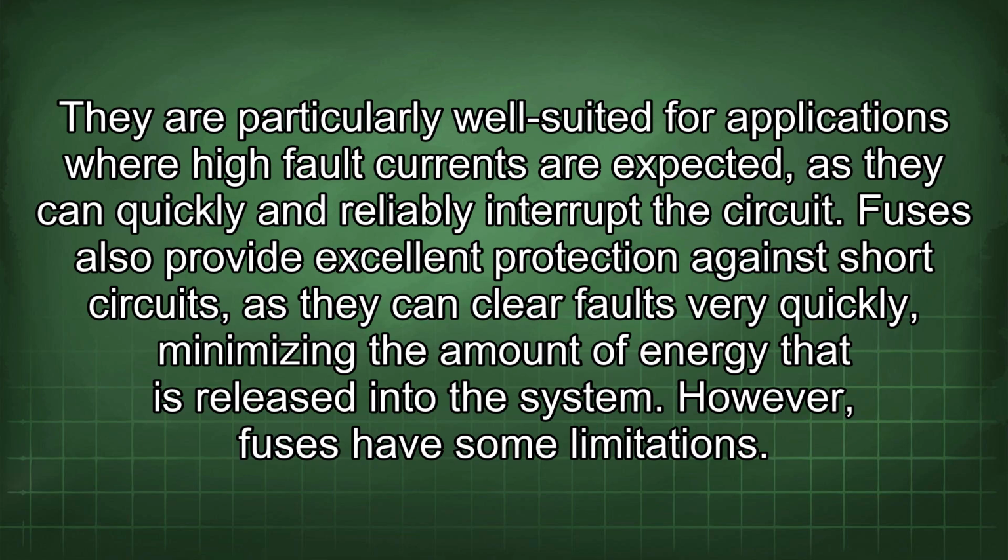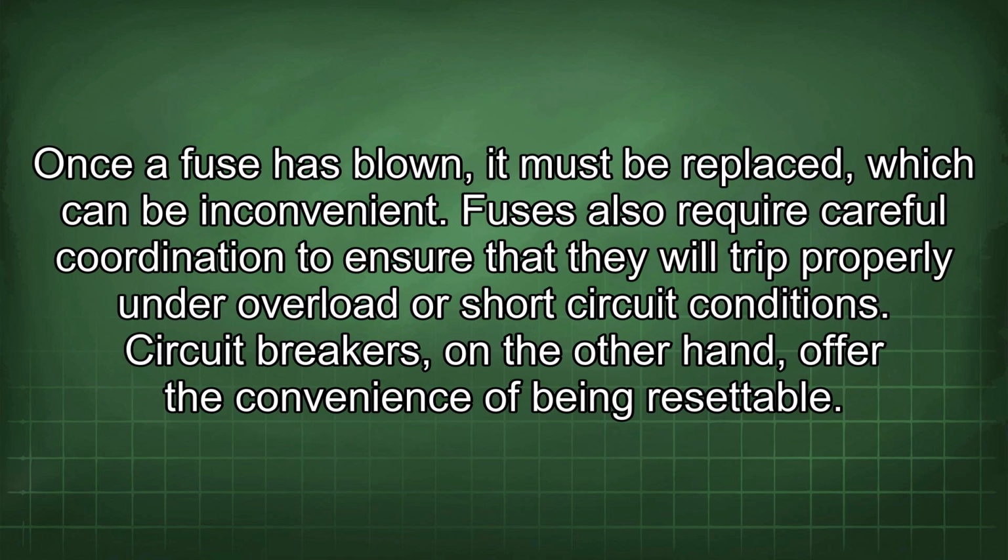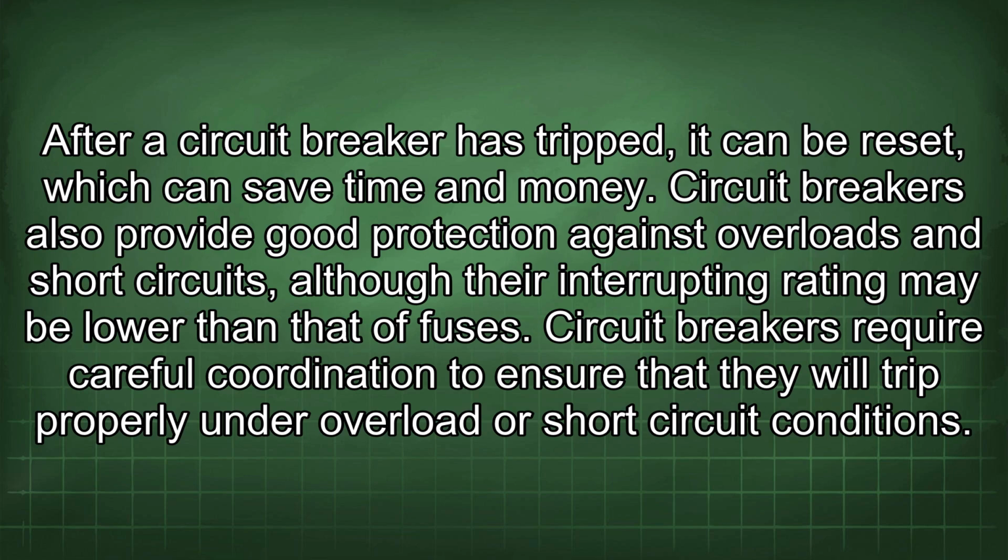However, fuses have some limitations. Once a fuse has blown, it must be replaced, which can be inconvenient. Fuses also require careful coordination to ensure that they will trip properly under overload or short circuit conditions. Circuit breakers, on the other hand, offer the convenience of being resettable. After a circuit breaker has tripped, it can be reset, which can save time and money. Circuit breakers also provide good protection against overloads and short circuits, although their interrupting rating may be lower than that of fuses. Circuit breakers require careful coordination to ensure that they will trip properly under overload or short circuit conditions.